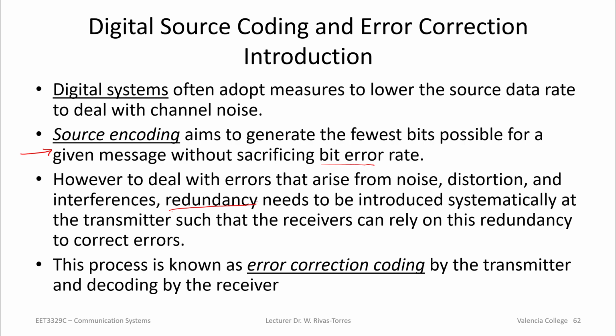One of the things that they do for this is differential encoding. So instead of sending the bits, you send the difference between 2 bits, and you're constantly doing that. So when the difference doesn't agree, you know that you had a bit that is incorrect. Okay, that's at a high level.